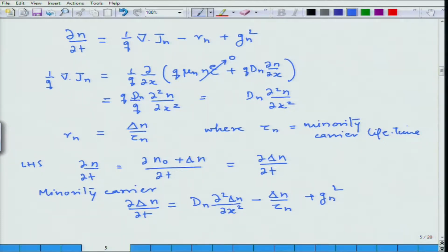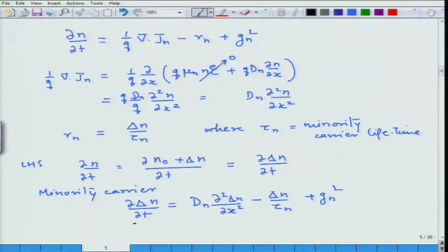So, I have changed this, and similarly I can write for the excess carrier concentration as well. What we have done here is change the continuity equation from one written in terms of the carrier concentration or electron concentration to the excess electron concentration, which basically means we are solving for what is happening to the excess electron concentration in a device. A counterpart of this can be written for holes also, for minority carriers.